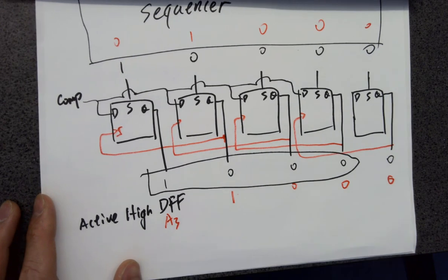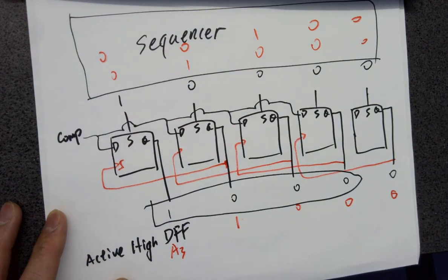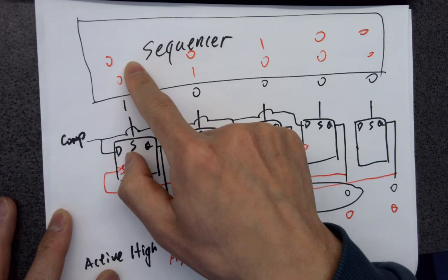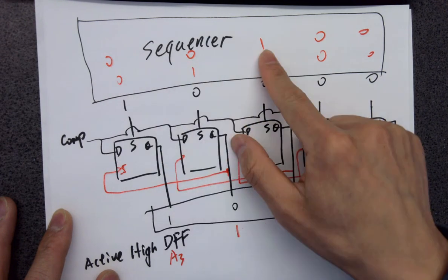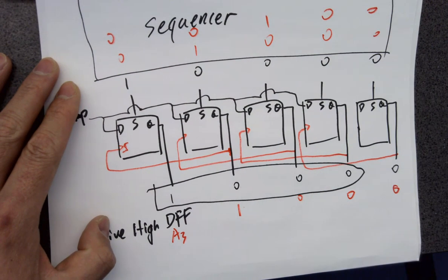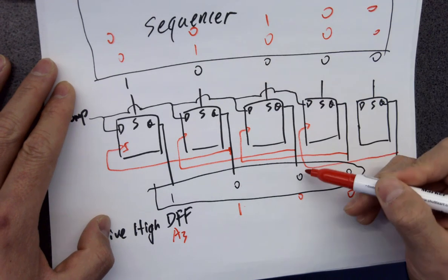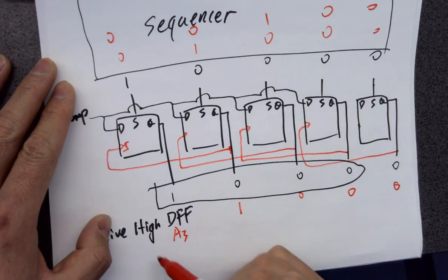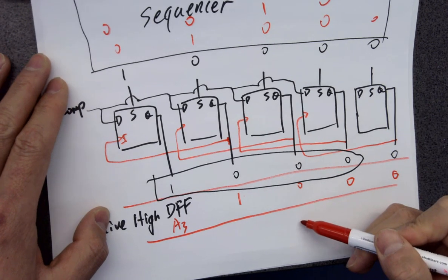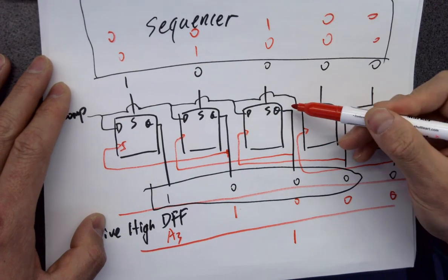Make sense? Okay. What about next? 0, 0, 1, 0, 0. So magically the sequencer is able to do this job. Look at the sequencer later. Okay, but now we assume that the sequencer is able to shift this one and plug zeros in front of it. Okay, so 1 is now shifted to here. What's going to happen? You see, 1 moves to this set pin. What's going to happen to this Q here? Being set, because 1 is arriving, so Q will be set.